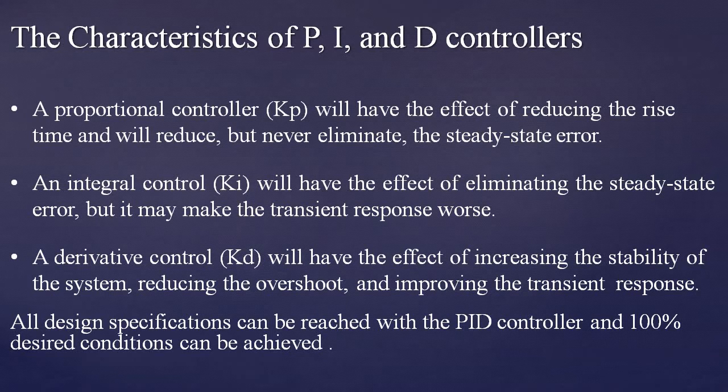Then the characteristics of P, I and D controllers. A proportional controller KP will have the effect of reducing the rise time and will reduce, but never eliminate, the steady state error.